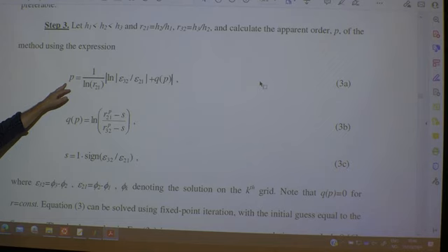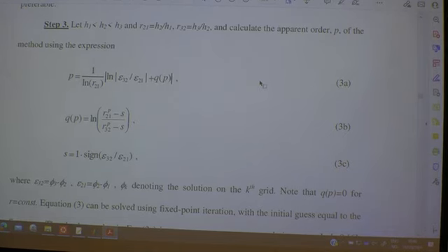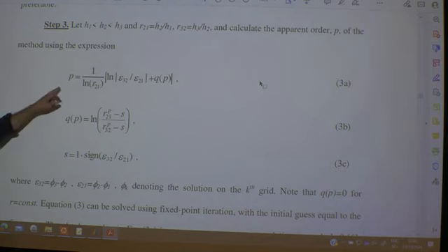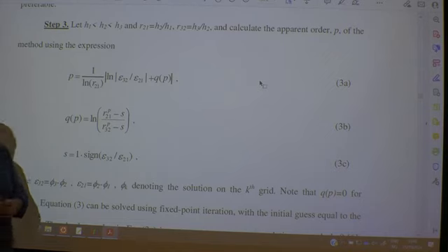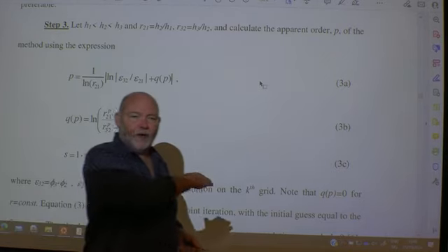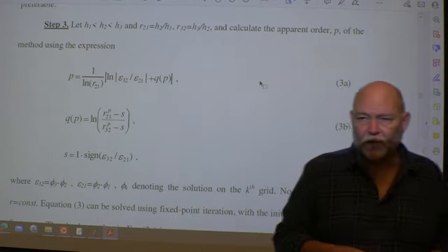We're using second order accuracy in space, and you should use second order in time as well to reach 2 seconds fairly precisely. So you just evaluate this one for the 8 different probes after 2 seconds, for instance. Then you may actually create one p average for all of these 8 curves and then use that value for the entire time history. We have to do something like that.